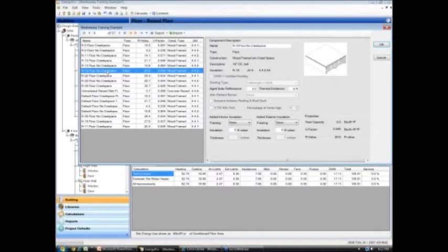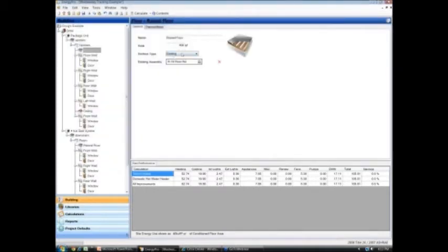Think about it for just a moment. That garage in the summertime in the Central Valley or in any hot area is going to get a lot hotter than a crawl space. So that factors into the calculations. If I say there's a crawl space, it knows that it stays relatively cool down there compared to a garage. So I just changed this to 400 square feet with an R19 floor. No, all that just means no crawl space.